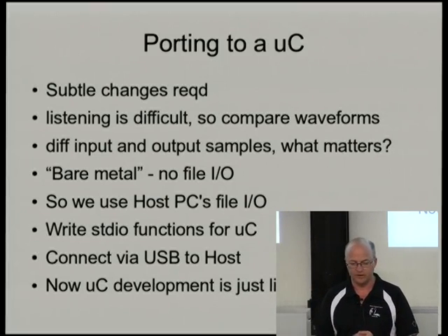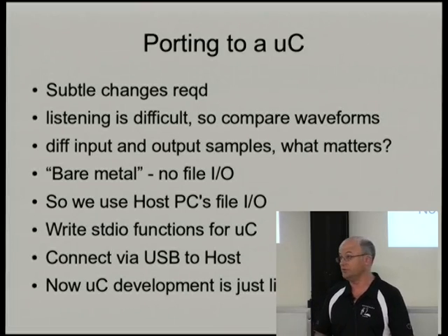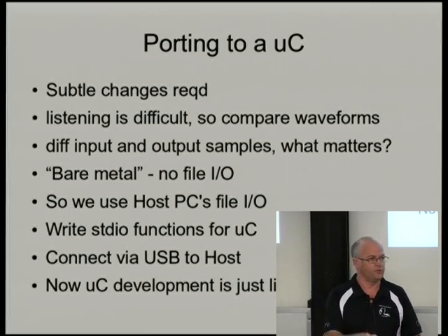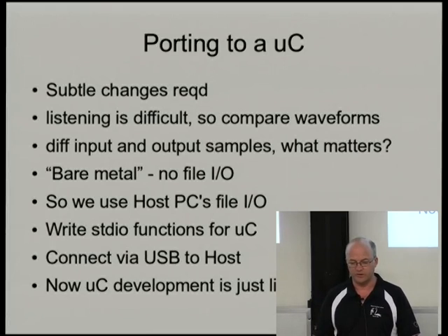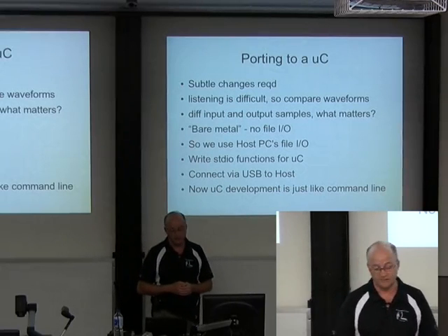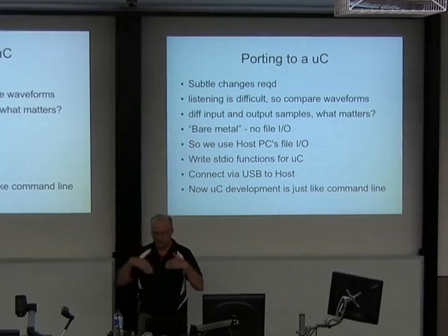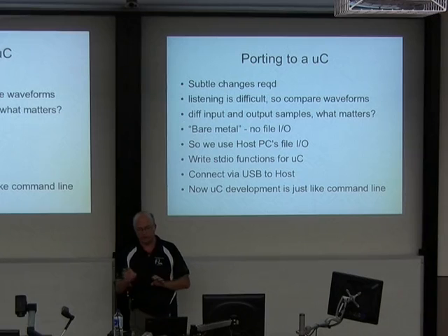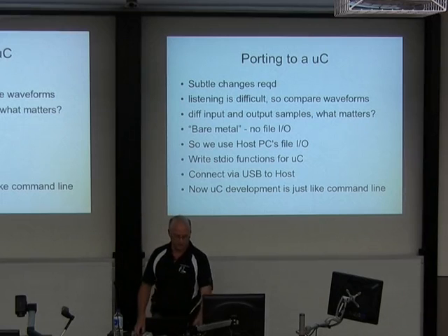So you have a GDB server running on the host PC and a little bit of firmware on the board that lets you access memory locations and things. What I've done is write an I/O subsystem, basically a subset of the standard I/O system for the microcontroller that uses the host PC's peripherals. So when the microcontroller code says printf, something prints on the PC screen. That makes it a little bit like using command line GCC debugging. You've just got the console, things print out, things get saved to files. That's all I have to worry about. I don't have to worry about moving memory buffers and GDB things on the microcontroller to see if it's working okay. So it turns it into command line GCC debugging.